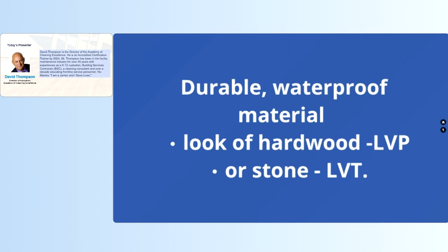Unfortunately, in the marketplace, everybody calls it luxury vinyl tile, and this is not correct because they are 2 different textures. We're going to talk about that this afternoon as well. So for those professionals that want to use the correct terms, you either have luxury vinyl plank or luxury vinyl tile. There are two others that we'll talk about very briefly, and that is roll goods and sheet. All of this is luxury vinyl. So when I use the term luxury vinyl, it covers all of these, what they call makeups.